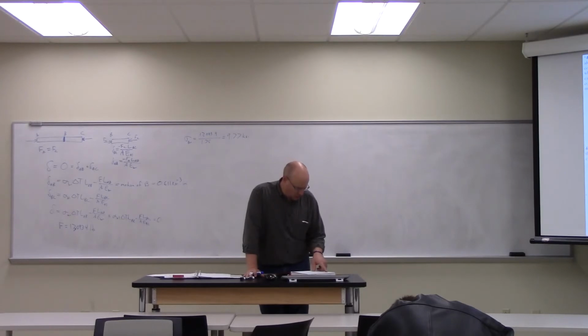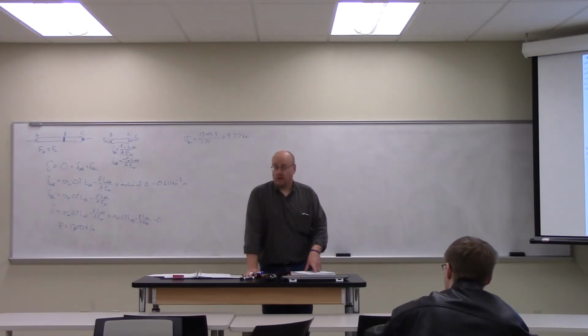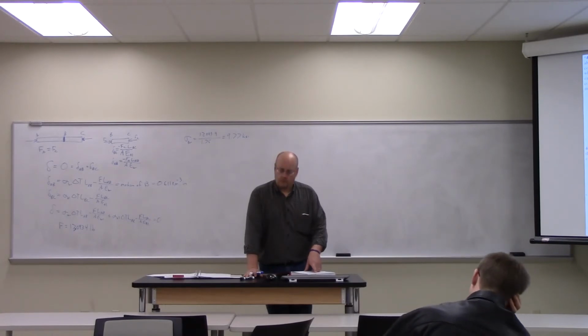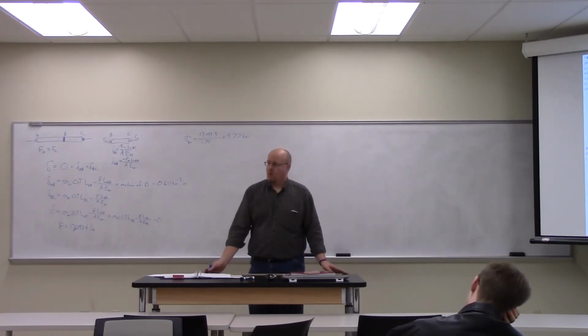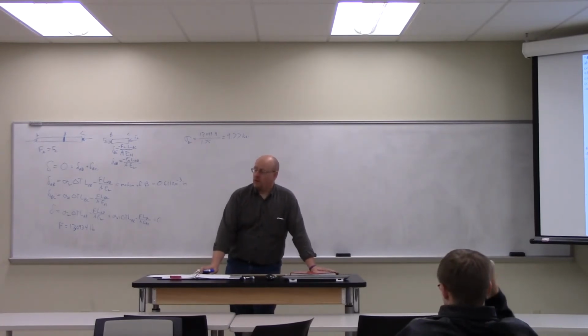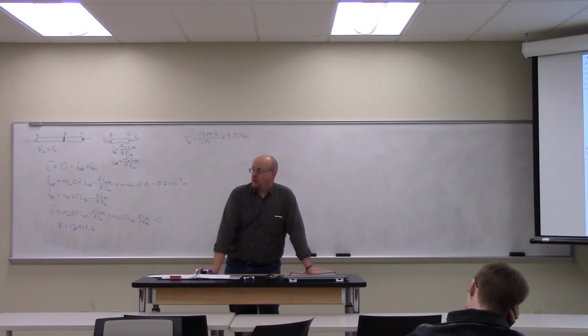And in red brass, the yield strength is 11.4 KSI. So we're much closer there, but it has not yet yielded. So it's still in the proportional range, an elastic deformation. It's squeezed, but if I cool it down, it'll go back to the way it was.